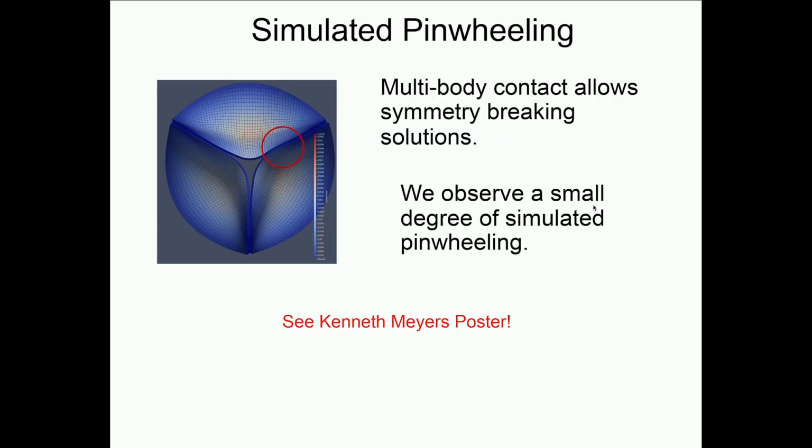When you have three leaflets together in a valve, because they're kinematically free, they can twist. It's called pinwheeling, and this was actually able to reproduce it. And it took about 2-3 seconds to run this.